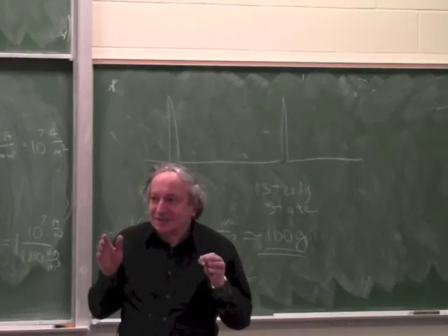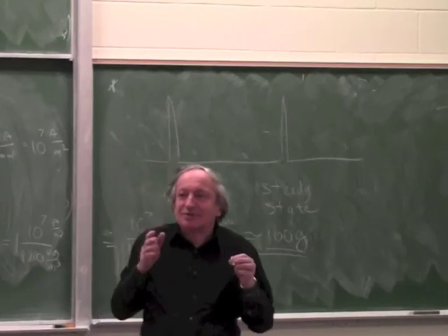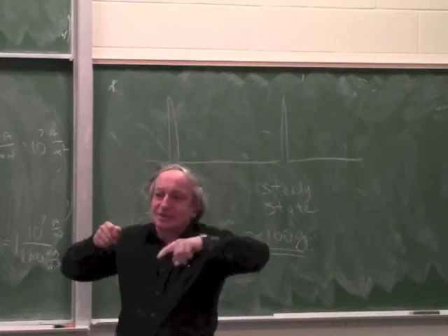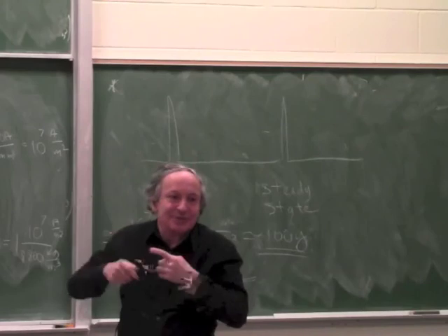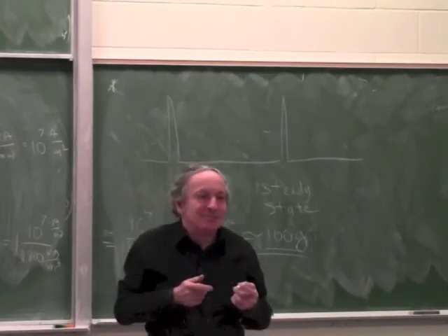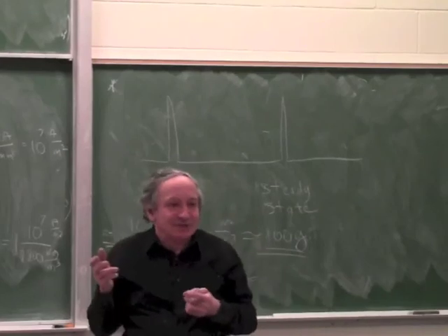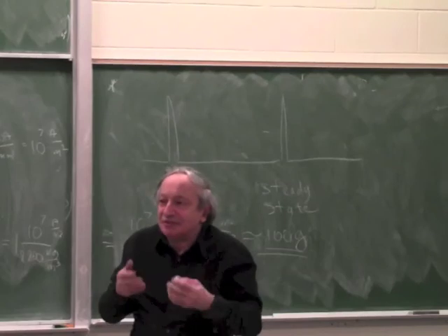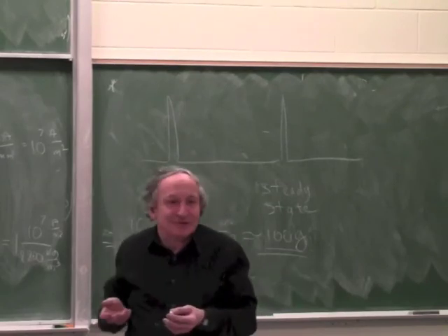Is that clear? Because otherwise you'd be tempted to think, maybe I can make a clever coil where one turn goes this way and another turn goes backwards to cancel the impedance. But it's a waste of time, because if you cancel the impedance, you cancel the stored energy, and if you cancel stored energy, you cancel the derivative of energy with respect to distance. It will give you no force.